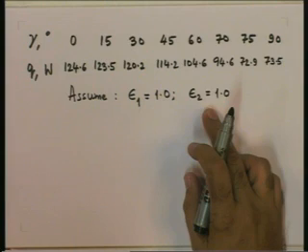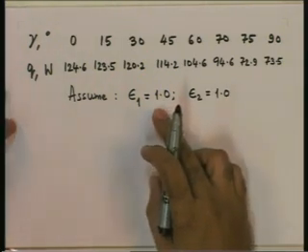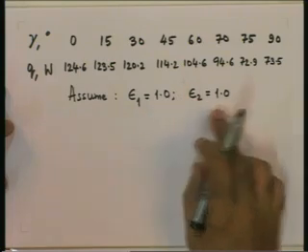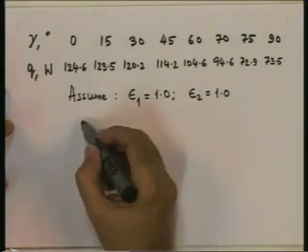For the glass surface this is a good assumption. For the plate surface this is not that good an assumption, this will typically be 0.8. However, assuming 1 will give us the highest value of radiative heat transfer.